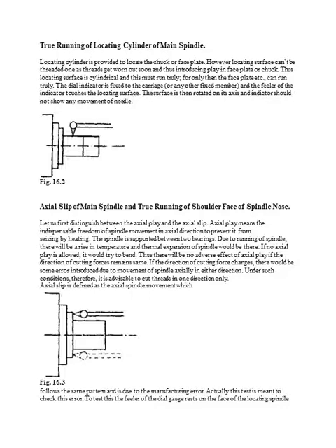Then the surface is rotated. Slowly it will be rotated, so the value of the dial indicator should not change. There should not be any variation. That means it is perfectly circular. There is no offset or eccentricity. So it should be checked using this arrangement.